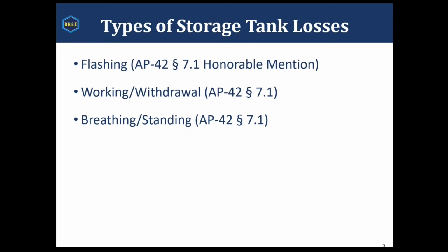We also have breathing, also known as standing emissions. Again, this comes from AP42 Chapter 7.1. The breathing or standing emissions happen as temperatures increase throughout the day. The temperature of the liquid sitting in that tank also increases, and some vaporization occurs because of that. So this is the liquid standing in the tank throughout the day, and it breathes or vaporizes some of the liquid as that temperature increases.